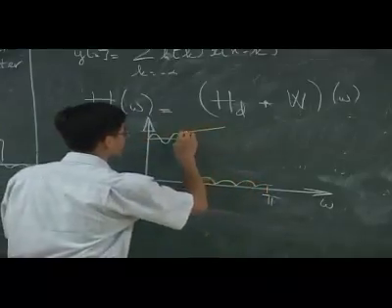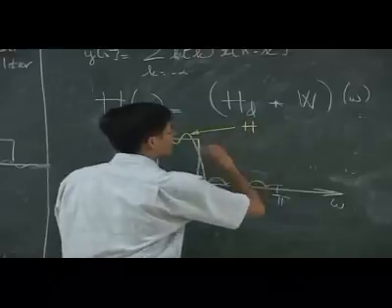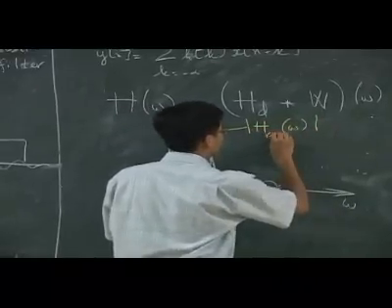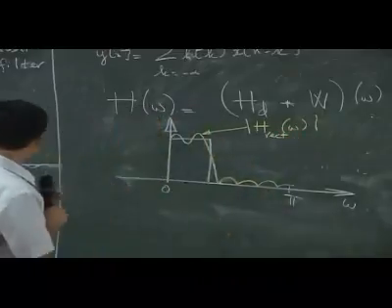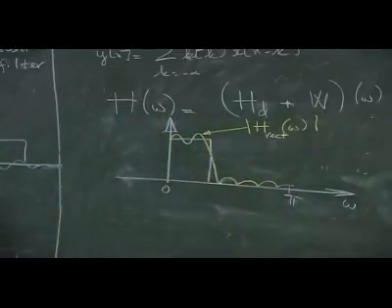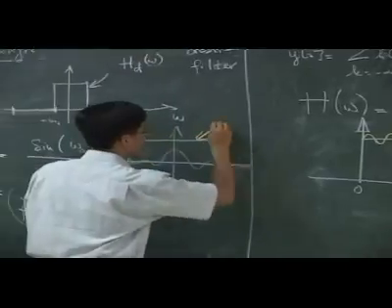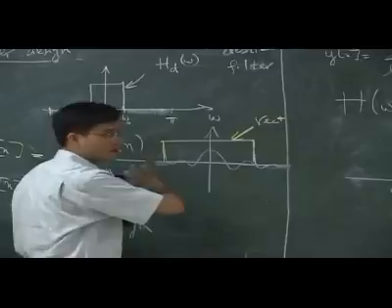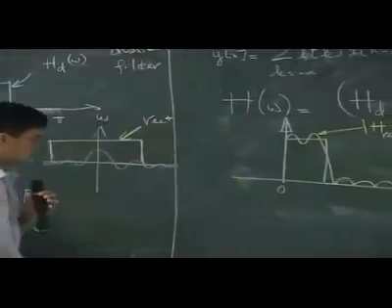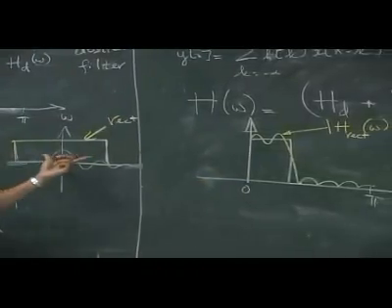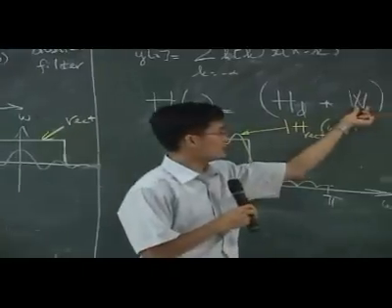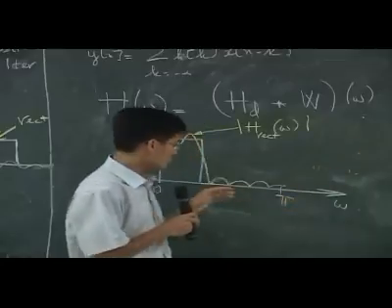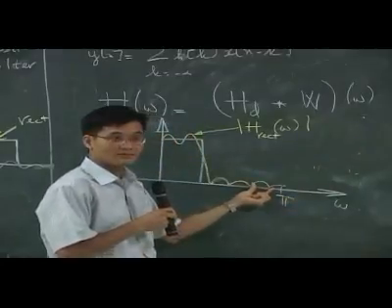So this is the edge, omega absolute value, using the rectangular window. I take a rectangular window, simply kill off everything outside. I got something like that. And remember this rectangular window, this thing is quite narrow, but it has a lot of wiggle. So the wiggle is going to create this wiggle here.